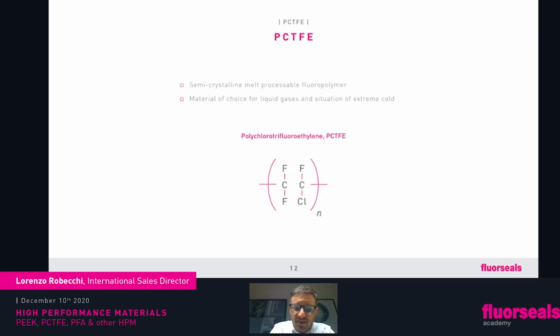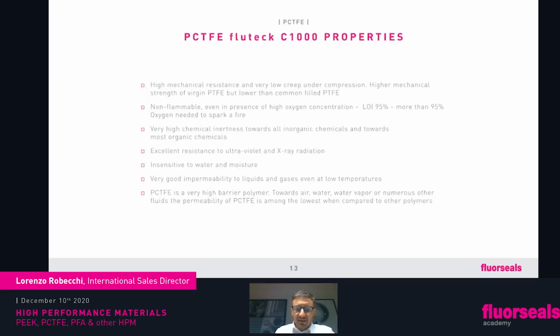Quickly, let's move to PCTFE. Let's go back to our family, to fluoropolymer. It is a semi-crystalline melt processable fluoropolymer, and this is the material of choice for liquid gases and situations of extreme cold.